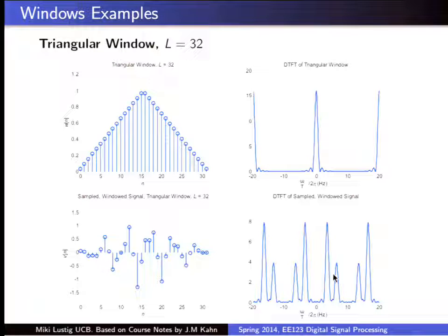Why do we have that trade-off one more time? You said larger main lobe, less side lobe. I mean, if you think about this, what is a triangular window? I mean, it gives more emphasis to the middle of the signal. So it's really just using an effective smaller number of samples, right? But the fact that you also multiply by a window is a convolution in the frequency domain. It's a convolution with a triangular function that is wider than a rectangular function. Okay.